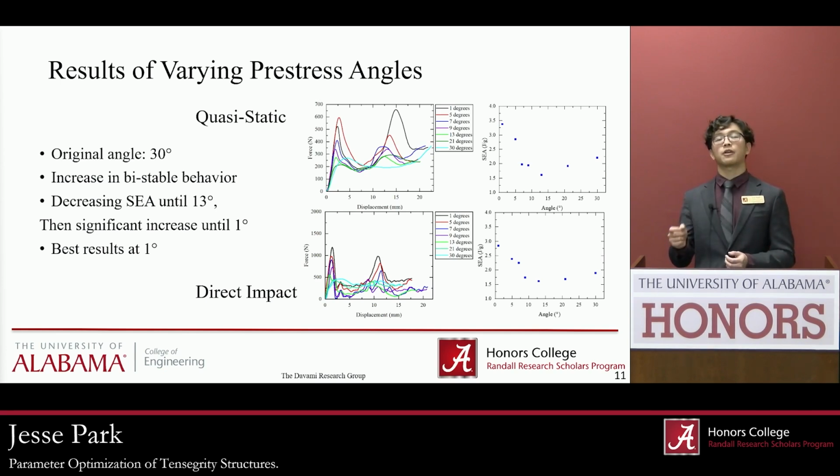However, the specific energy absorption actually decreased up until 13 degrees, which we initially thought might have been concerning for our results. However, we saw that after that 13-degree point, with decreasing angles, it drastically increased up to our optimal pre-stress angle of 1 degree.